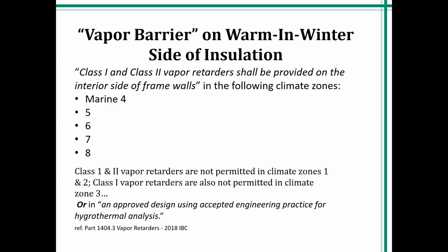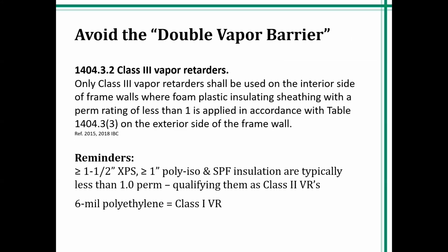They had this impermeable ice and water product, which was not necessarily, I guess at the time, dedicated as an air barrier when they should have had a vapor permeable air barrier. So that's, I'm getting ahead of myself here, but that's typically when we would very much want to see a vapor permeable air barrier. So anyway, I've seen a lot of things, sort of like in a certain TV insurance commercial. I've seen that thing or two. So again, avoid the double vapor barrier condition.